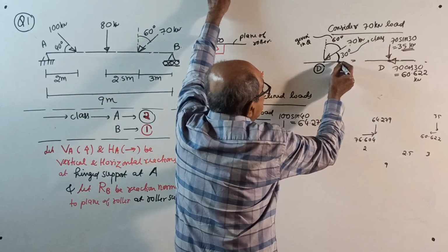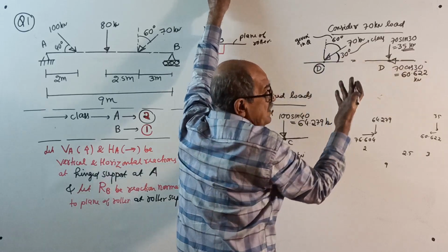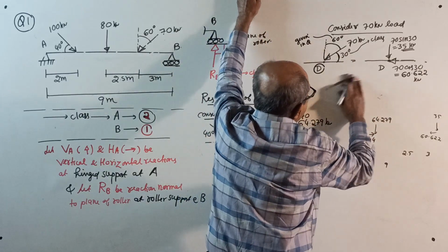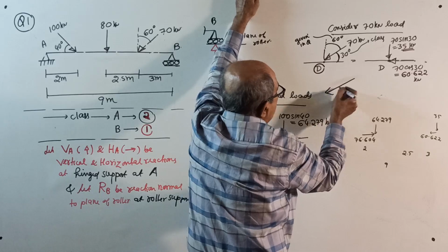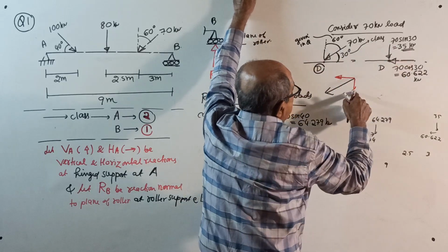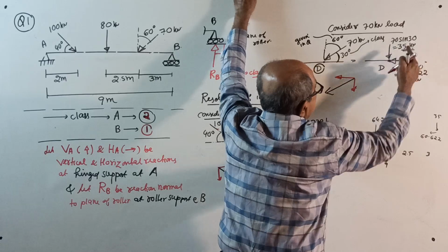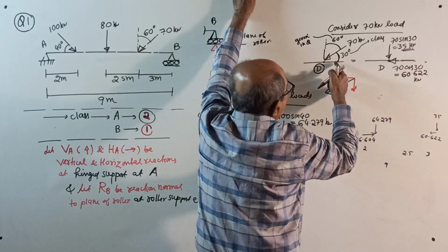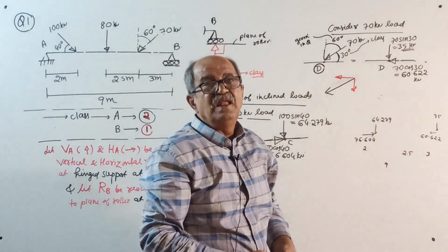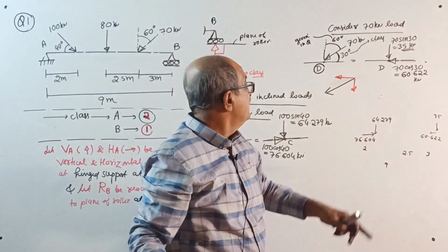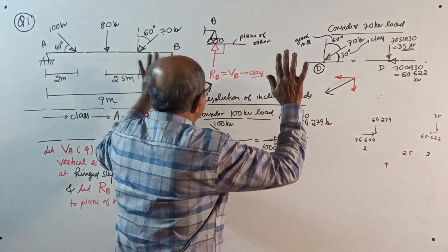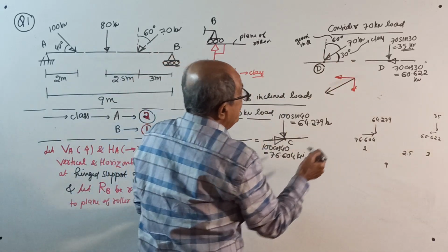So if you consider this 30 degrees, you don't have to bother. This force is like this, so it will have one horizontal component to the left side and one downward component. Vertical down is 70 sin 30, horizontal component is 70 cos 30, because we are considering the angle with horizontal. Some will tell, sir, you told this 100 times earlier. But again I am telling, next time all this I will not explain. First go for resolution.